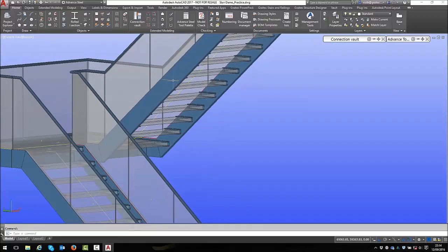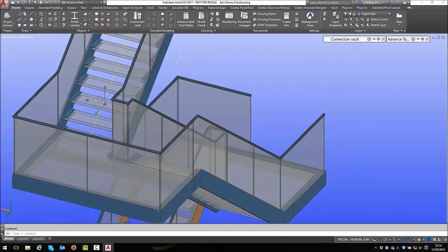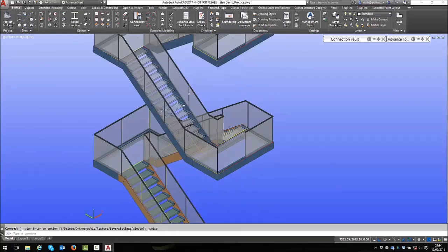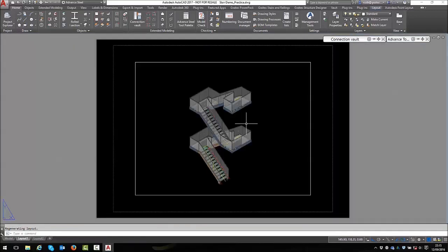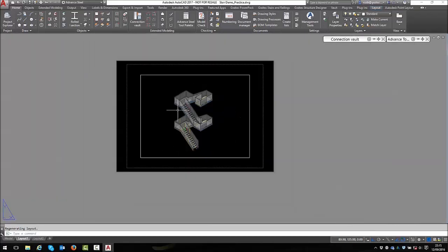So that's how I created the stringer. I had to go into the table to enable the stringer to turn it into glass. I can't actually see glass. If I created the drawings for that, it would just show that as a plate, hidden detail behind it. What you can do, if you wanted to, I can go to a layout here, look, and if you knew anything about viewports, I can add viewports, I can add the different views in viewports, and I can create that. Nothing's stopping you doing that.